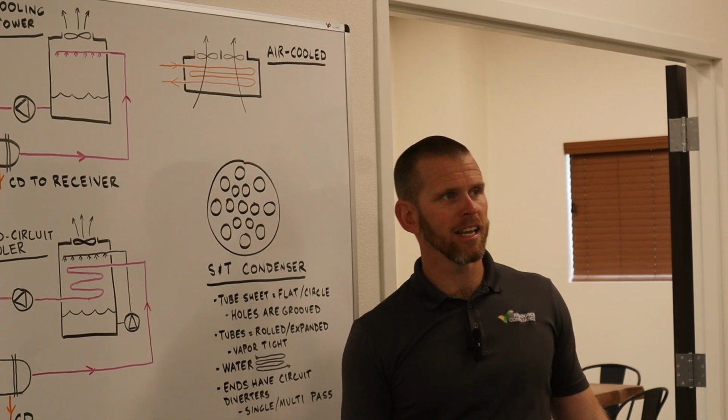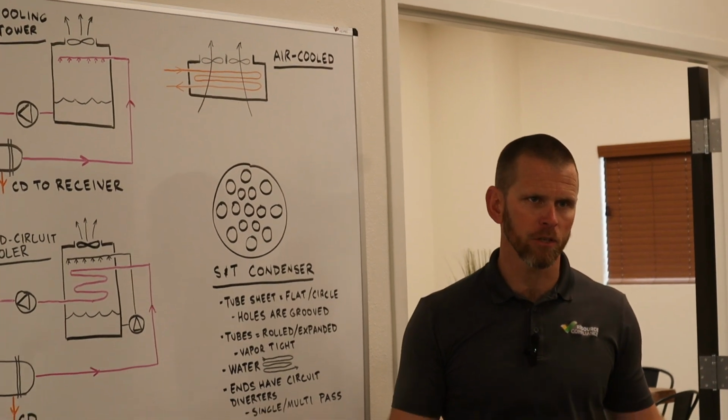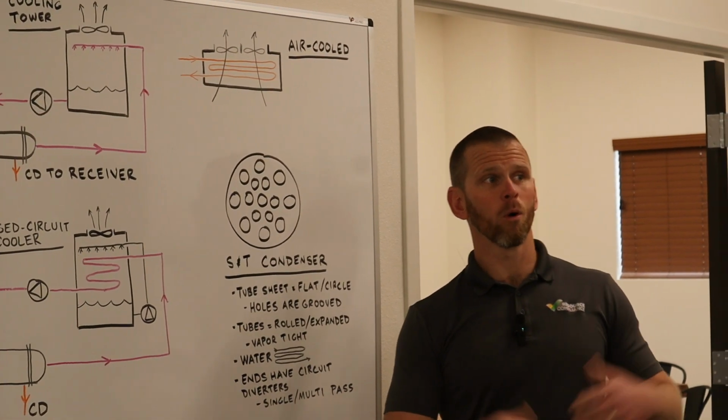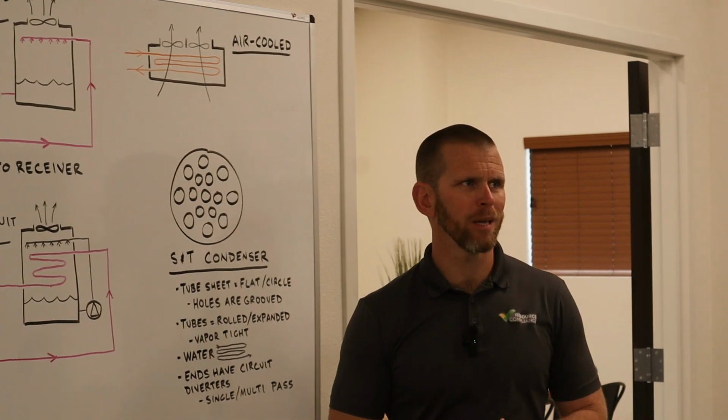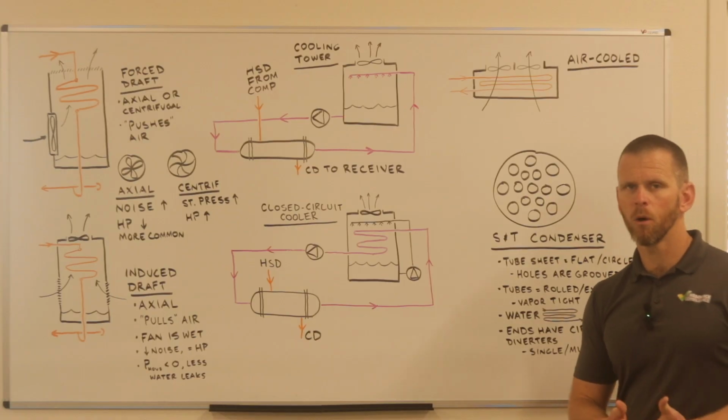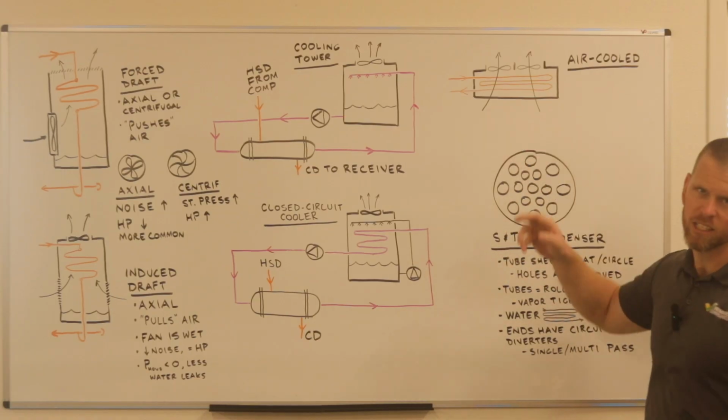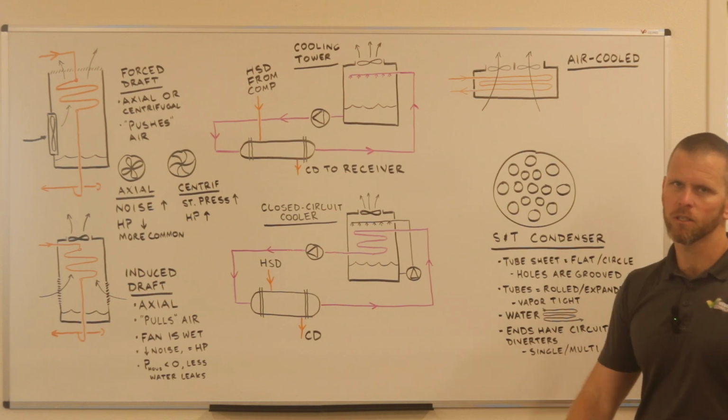Unfortunately, the downside is it's going to result in higher discharge temperatures, a little more electricity costs, generally speaking, and especially when it comes to ammonia refrigeration, that's a problem because of ammonia's high theoretical discharge temperatures.